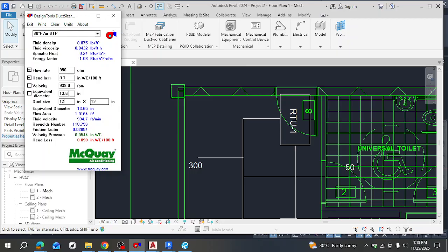So I just took a value that is close to 13, which is 12 in this case. That's how I got that 12. Yeah. So when doing duct size, I like to round down, not up, because smaller ducts tend to be able to carry air farther than larger ducts.